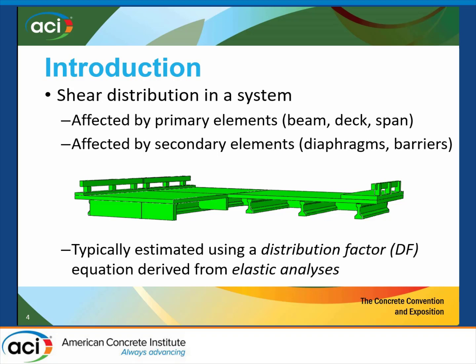In the United States, at least, this is often estimated using what's called a distribution factor, or DF, where it's really just an equation that's derived from elastic analyses. So no failure loads, no cracking, just elastic behavior, to come up with an equation for distributing the shear force.